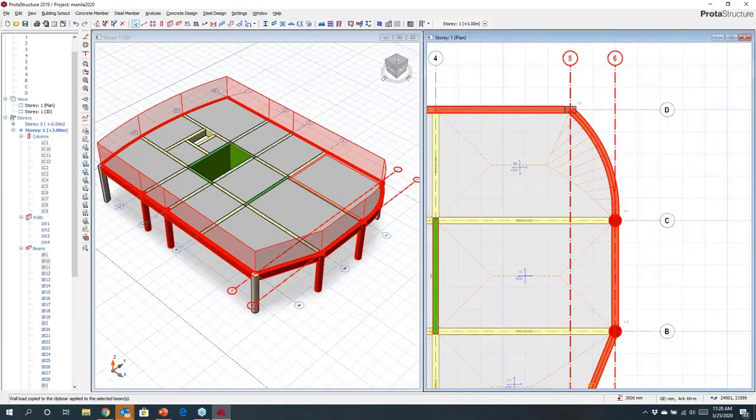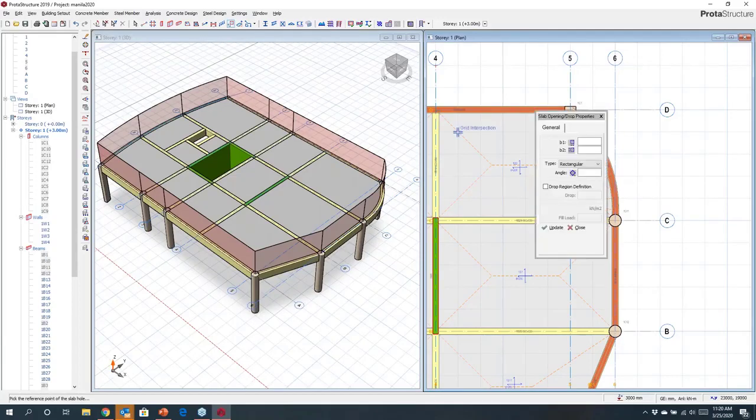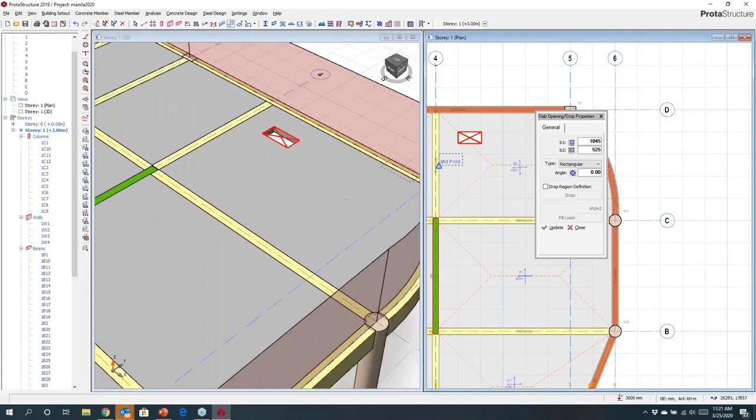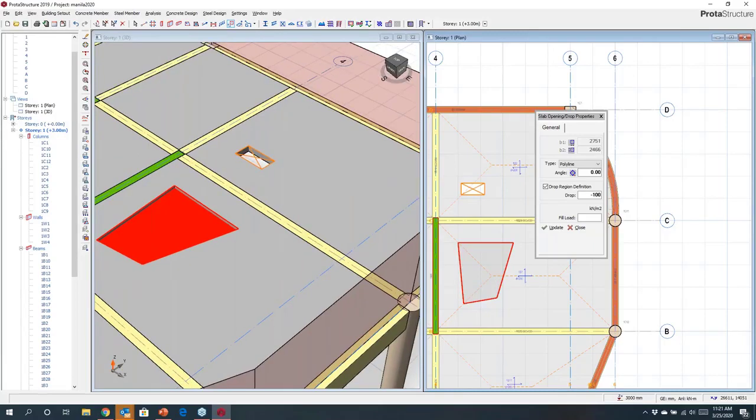We're working with a physical model, so you can lay out other things within the model. Here I'm going to put in, say, an opening, and you can see physically that that opening's been created in the model. The beauty of this is it's not an analysis solution; it's a proper physical object. So if I got the position of that wrong, I can easily just pick it up and move it around to suit. Okay, if I have other things going on in the slab, you may have drops and the like that you wish to define. You can come in and easily create those within the model. So think of this as I'm going to be creating exactly what I might see for construction on site.